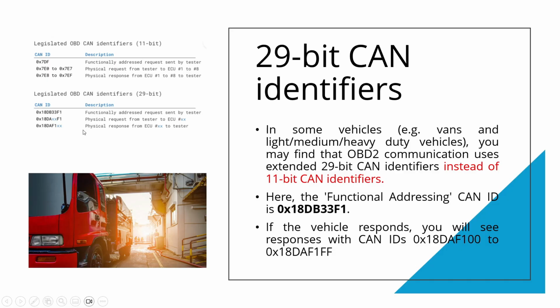If physical addressing mode communication is initiated by the testing equipment, then the particular ECU will respond with the CAN ID of 18DAF1XX, where XX represents the particular ECU.